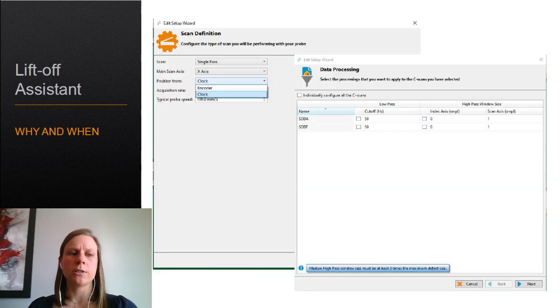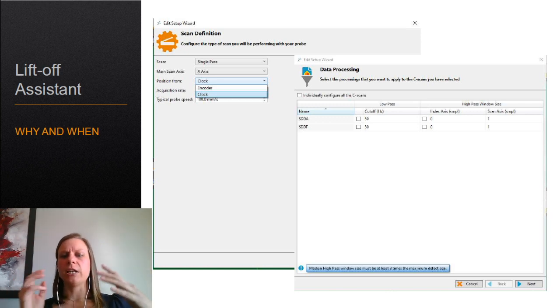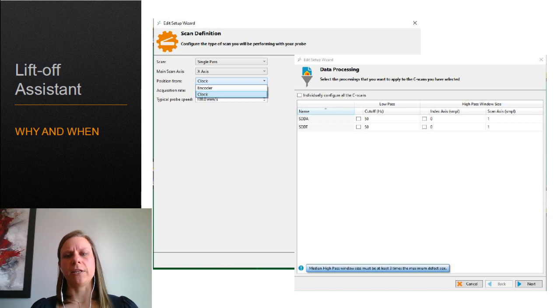With the current state of things, so with how it's made right now in most of the software, you need to go deactivate those encoders and filters manually. So that's a couple of different windows that you need to access, do the rotation, and then go back and reactivate everything. So it's multiple manual steps, and there are risks to forget something along the way.